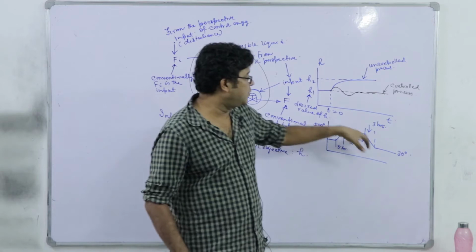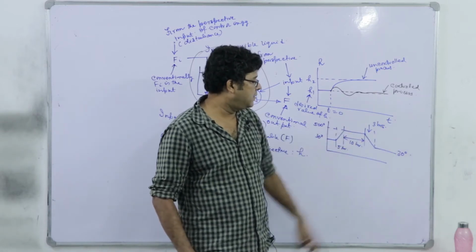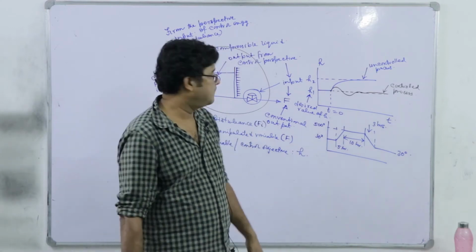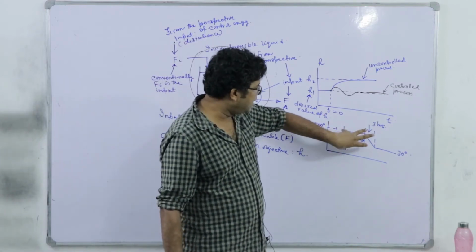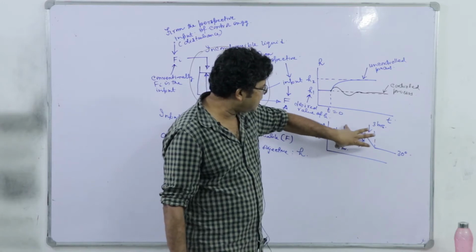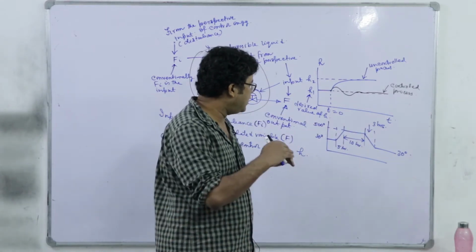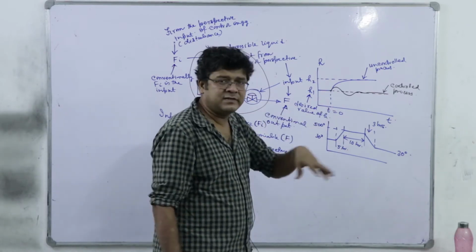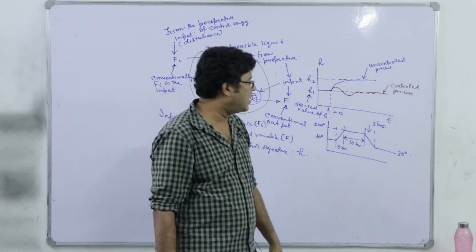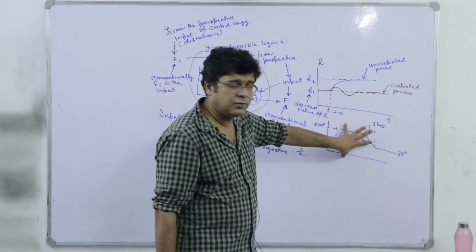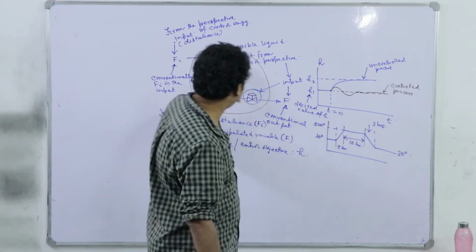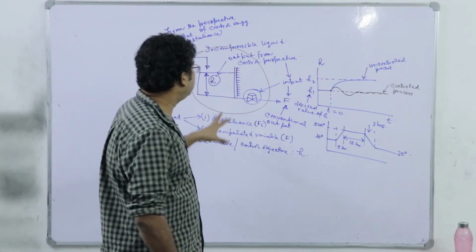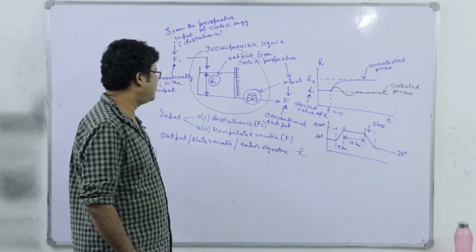However, the temperature is to be changed following this specific pattern. So we have to control the device, right? This type of control strategy is the control problem where the desired value of that variable is progressively changing because of certain special requirements. It's a special type of control known as servo control, whereas this one is called regulatory control. We will discuss it in detail once we go for understanding feedback control.